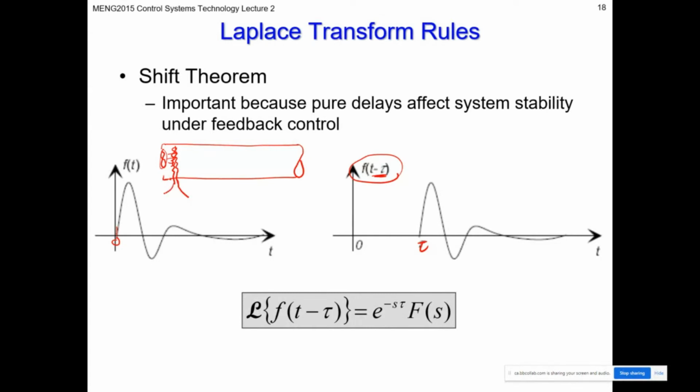Say we have a rheostat controlling the heating function, and we apply, at time t equals 0, a voltage on this rheostat, which is linked to a heater, which is heating the air blowing through the pipe. We have a step input. This is our step input, and the voltage goes up to 10 volts.